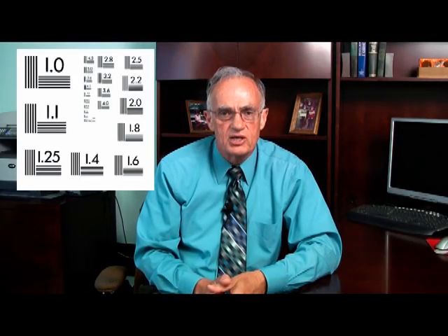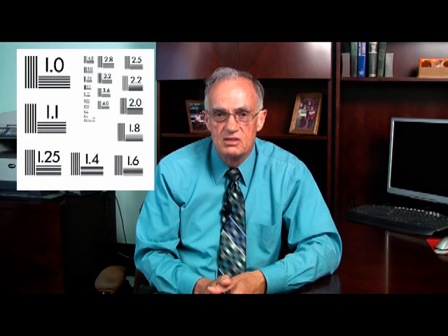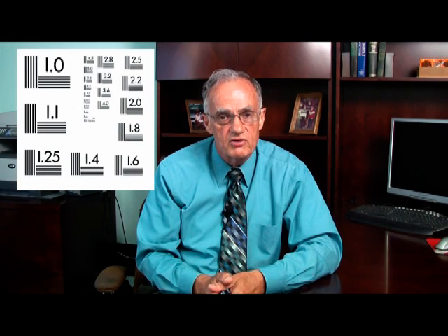You can also buy commercial resolution targets. These are especially useful for smaller fields of view. Whichever target you use, make sure that you record the limiting resolution, and also save your vision system's image of the resolution target for future reference. Now you know about benchmarking imaging resolution, let's return to the lab to see about the next benchmark measurement.